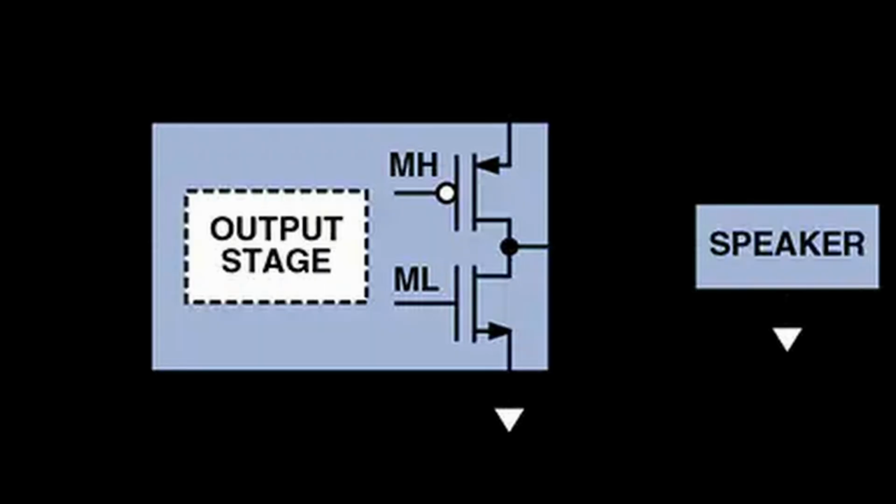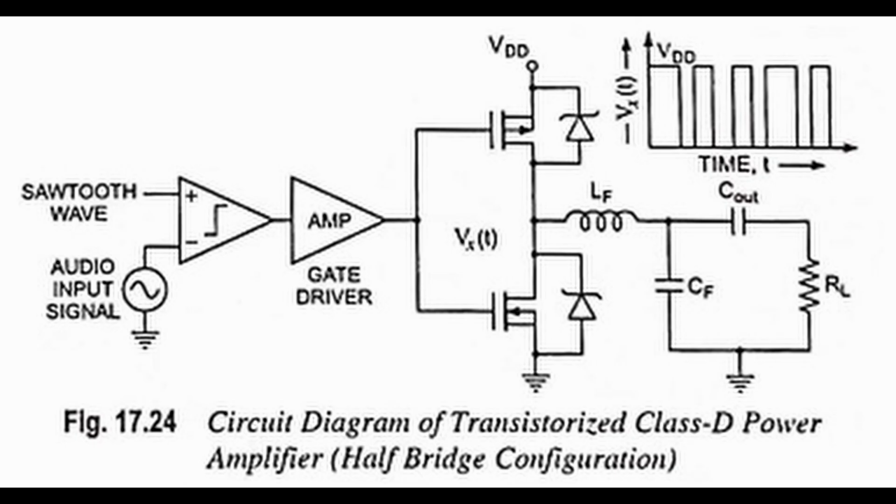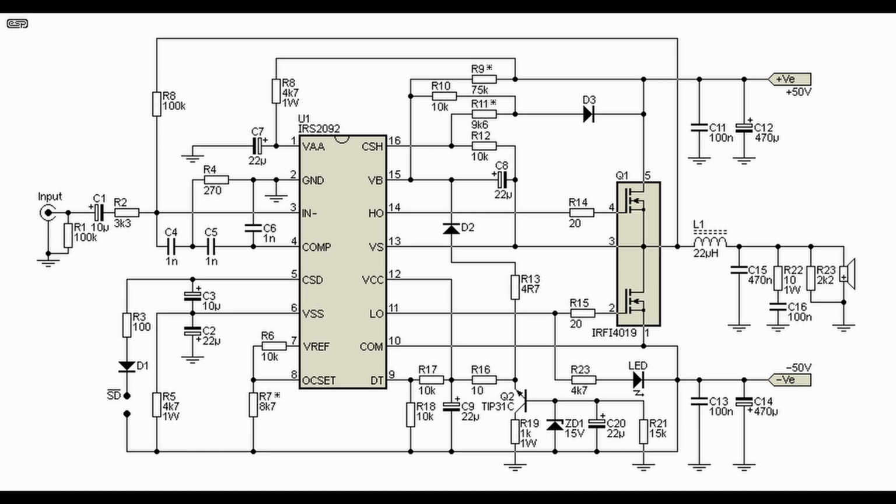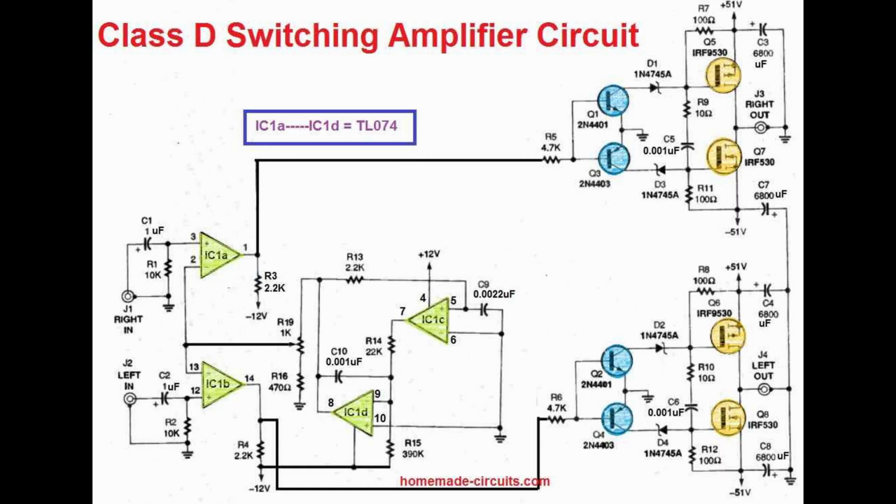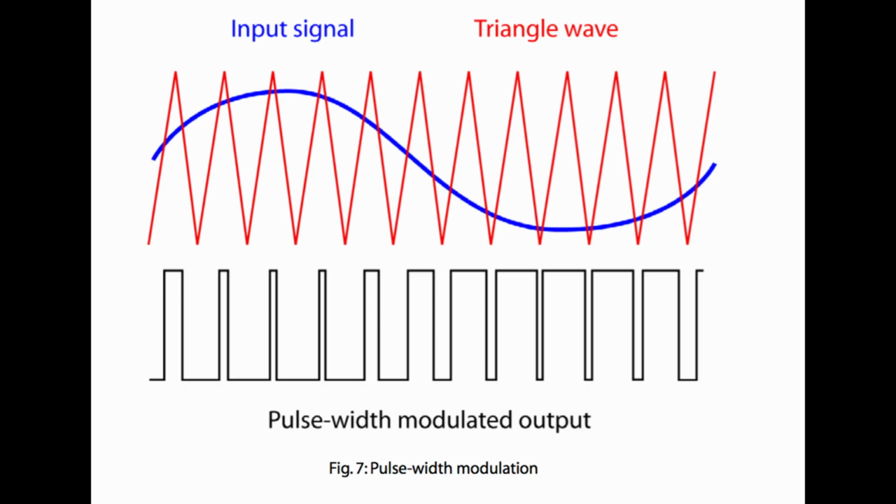GaN transistors, specifically GaN HEMTs, have this amazing property. They virtually eliminate something called the reverse recovery charge, or QRR. QRR, okay, what was that doing? In traditional silicon MOSFETs, that reverse recovery charge was a massive headache. Every single time the switch turned off, this charge caused ringing, noise, electromagnetic interference, or EMI, and just generated extra heat. It was a primary source of switching noise and loss.